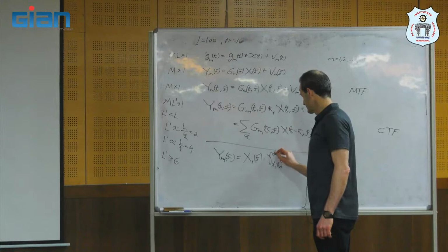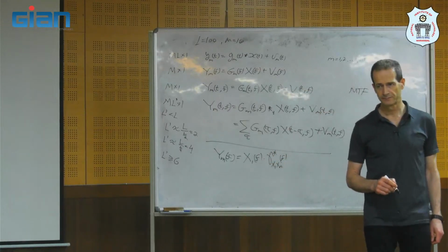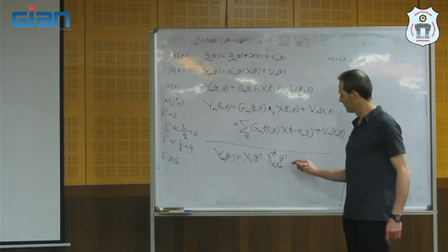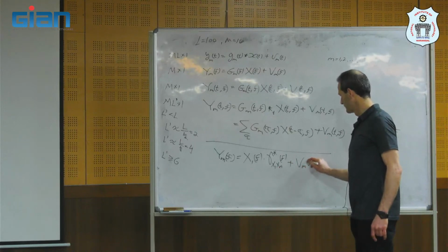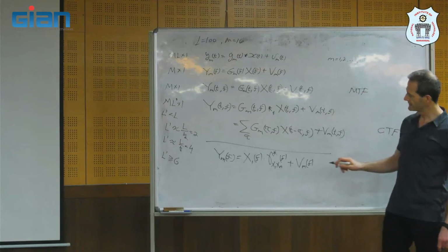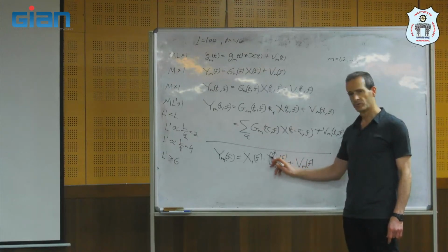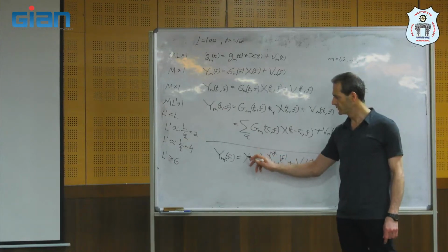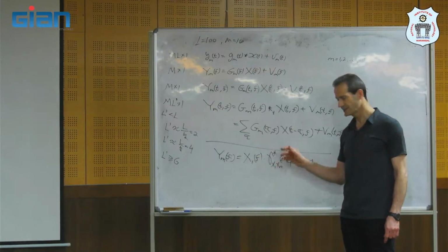This is the partially normalized correlation. We defined it, okay? So we have here plus noise. For signal enhancement, we showed that this is actually the relative transfer function between xm and x1.